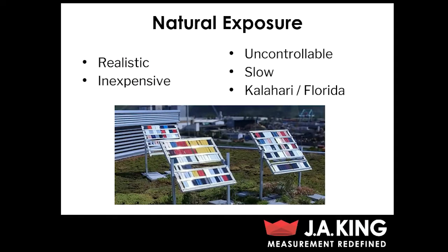Also, natural exposure testing is quite slow. If you want to simulate 10 years of solar exposure, you really have to take parts and let them sit outside for 10 full years. So oftentimes people are going to opt for more accelerated testing, and we'll talk about those methods here in a minute.